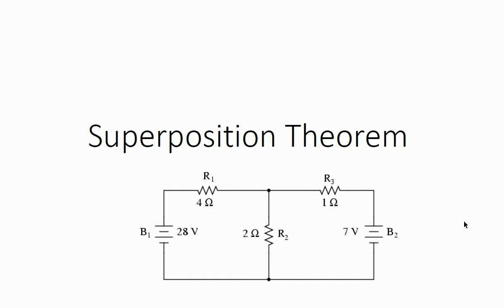Now, the voltage drop is very straightforward. You've got a current flow, you've got a voltage drop. The voltage drop happens inside the battery, so there must be some sort of hidden internal resistance. We can't see it, it's not a resistor, it's nothing tangible, so it's some sort of hidden resistance. And that is what's represented in these circuits.